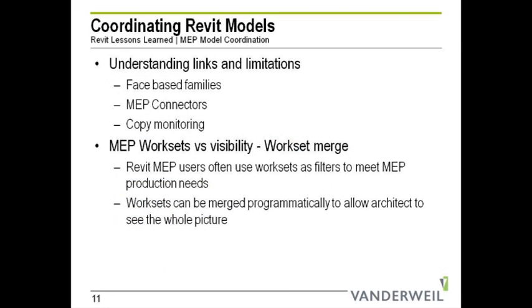Now, as you're working with consultants, you're usually going to be dealing with linked models, as opposed to all within the same model on the same network. Because your consultants are going to be using your model as a linked model, there are a few things to understand. Your consultants are going to be using space-based families as opposed to hosted families. These space-based families are still going to be associated with and hosted to your wall, your ceiling, your model.